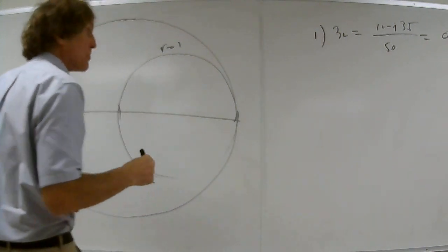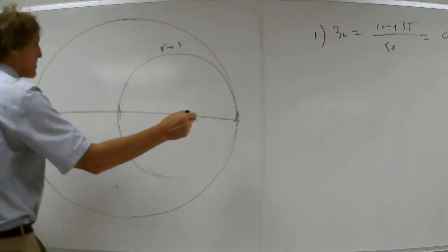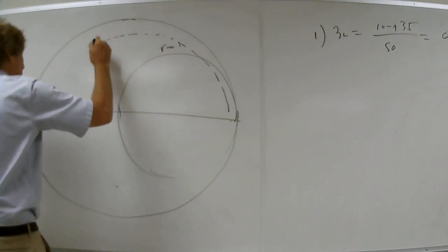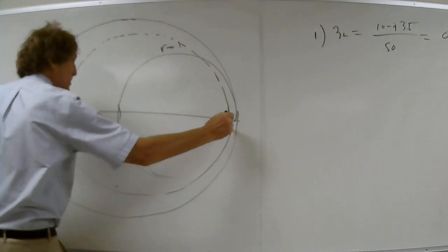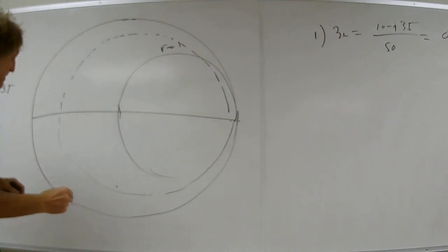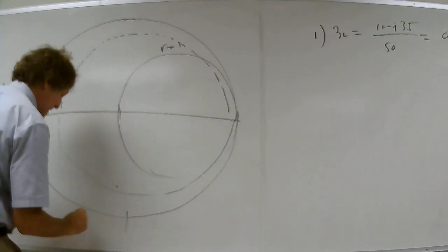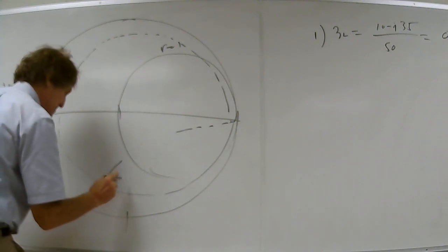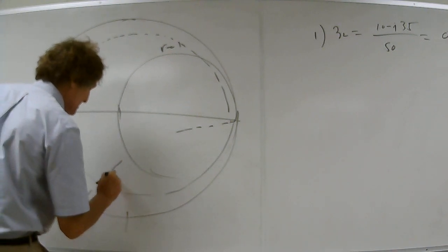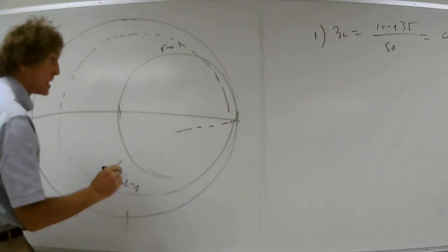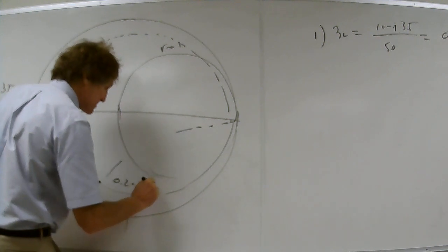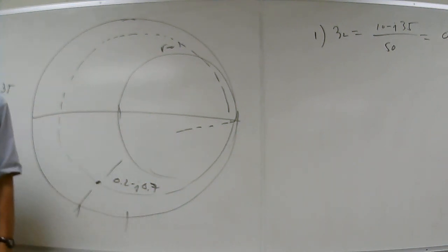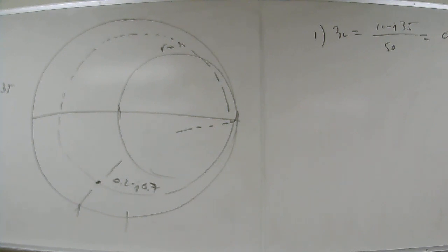All right, let's locate that point. We've got 0.2. Now that's a circle. Take a look, that's way out here, isn't it? Look at that trajectory, 0.2 for the real part. And then minus J0.7 is down. This is minus J1, so it's about here. So your first point should be about here, 0.2 minus J0.7. Can you all see that on your Smith charts? Yeah, it's about there. Make sure you can find it. Chase, can you see this? Yes, sir. All right. You good with this?